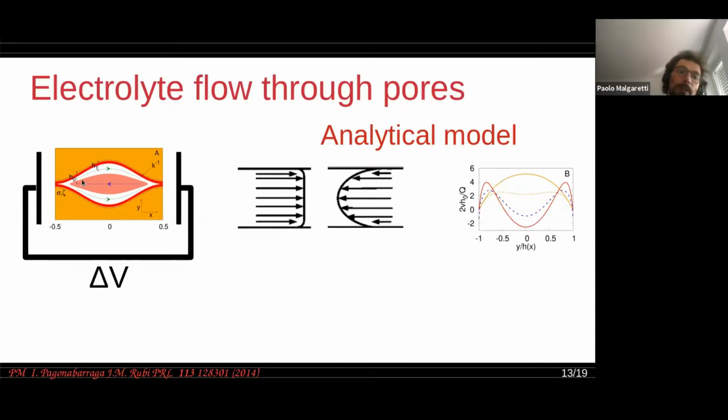So the fluid is going, so to say, rightwards, as it should, because of the delta V, close to the walls, but at the center, it is going backward. And then in practice, you're generating some vortexes that at low Reynolds number are typically called eddies. And these eddies are quite important because they can, for example, enhance quite a lot the mixing inside this channel. So, for example, if you have a chemical reaction, it can be good to have from time to time this kind of device to enhance the mixing of your chemical reactions, such that you keep all the reactants in contact with each other.